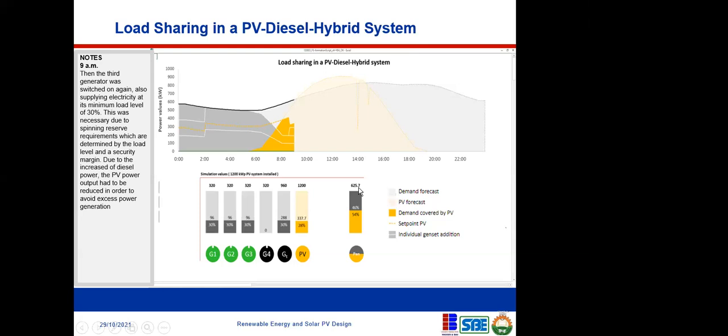because you're not having 625.7 kilowatts as a load. If you're running only two generators, remember you must have 5% spinning reserve, greater than 5%. So if you add your spinning reserve of more than 5% plus these two capacity, it will be less than 525. So you need a third generator to come up to cover this.